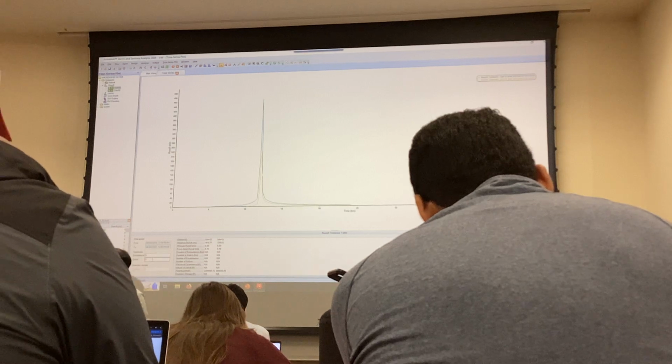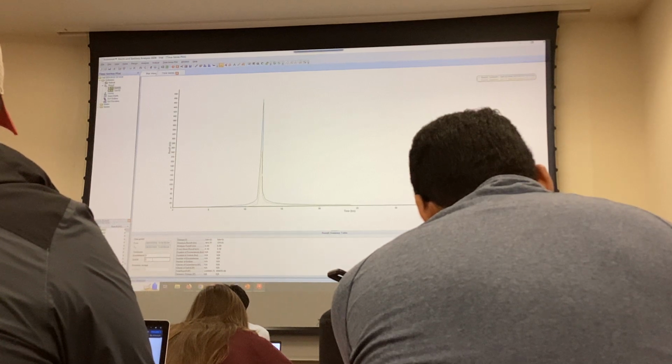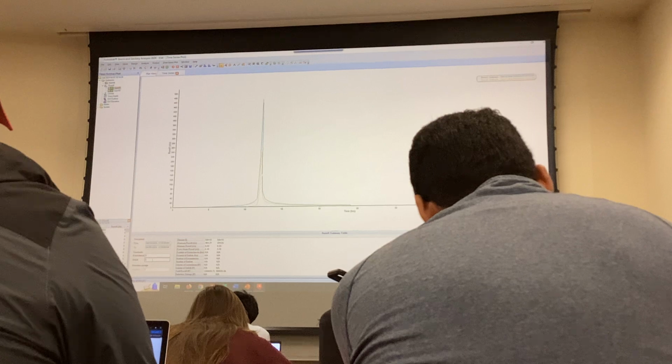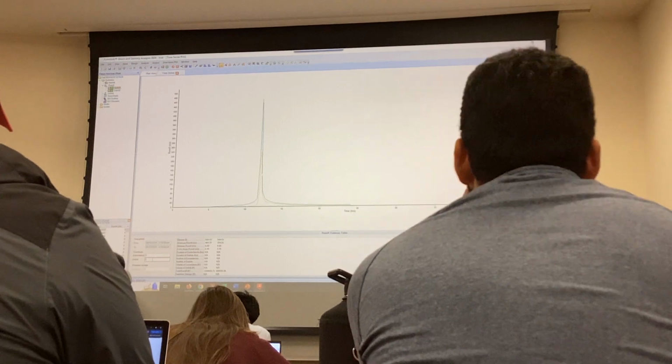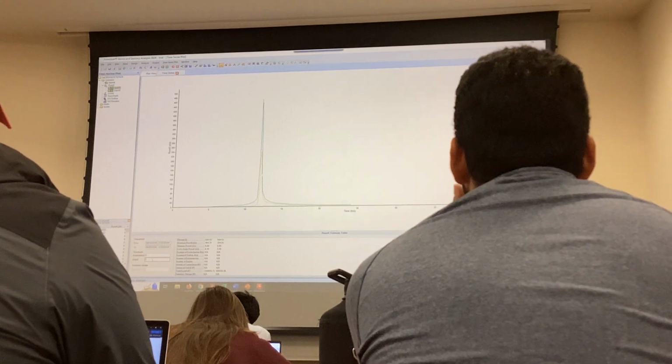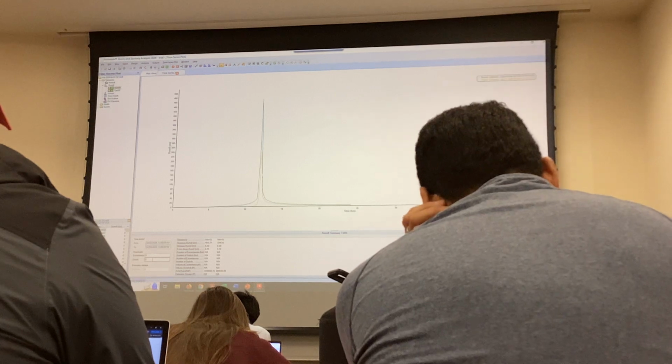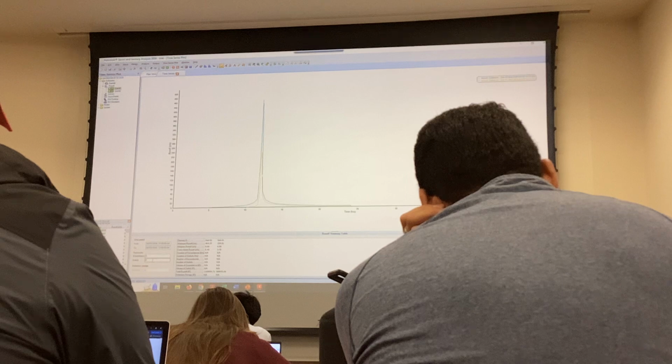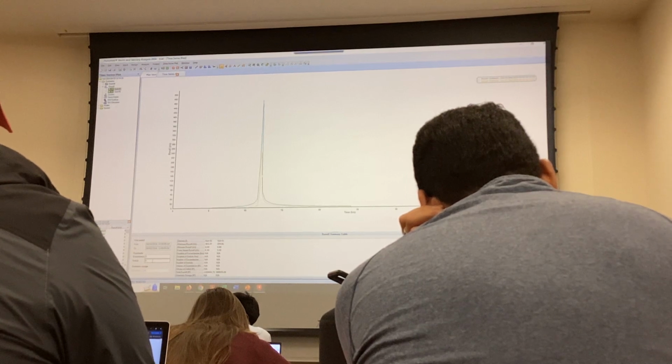Okay? So that's not the end of this because I haven't shown you how to do your detention, specify your detention basin. I haven't told you how to specify your outlet structure, right? So that will be the next step. So now you have a hydrograph and you know what the volume required is. Now you can go in there and tell the program the detention basin that you actually carve out on your AutoCAD drawing to detain the water.